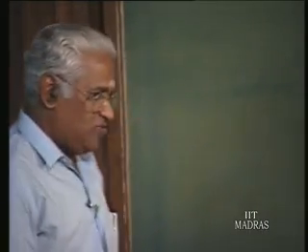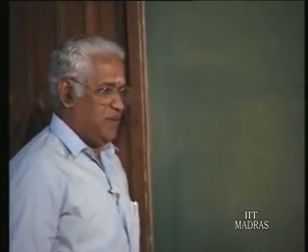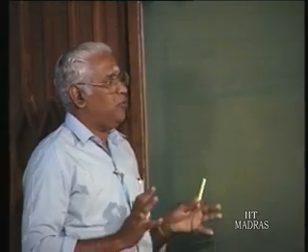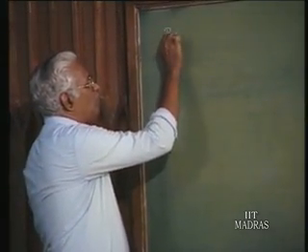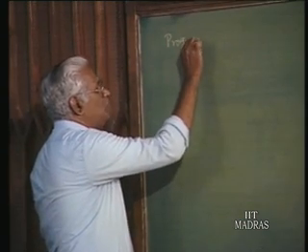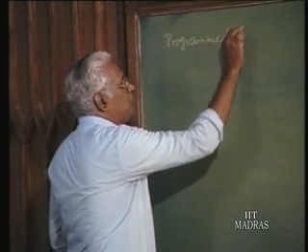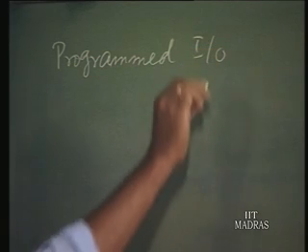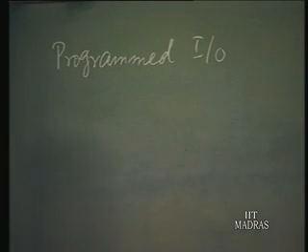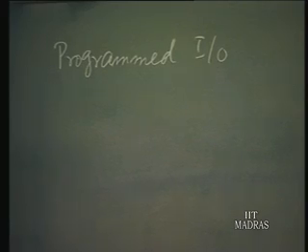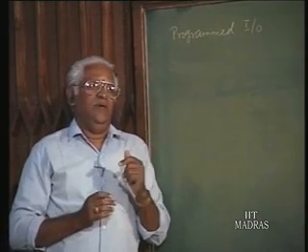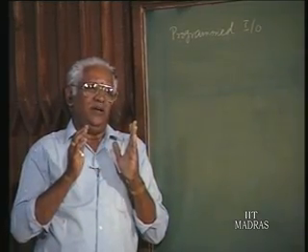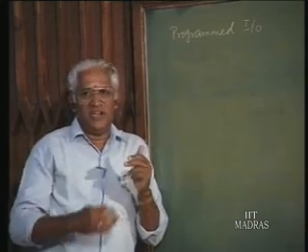Let us look at some details about each of these modes of data transfer, essentially what the programming will look like. Now, if you take programmed I/O, that is the very first one, essentially it would be first checking the status, and then doing the data transfer. Now, I think I will skip some of these things. Suppose you want to transfer say 5 bytes of data, and assuming the device is a byte oriented device,